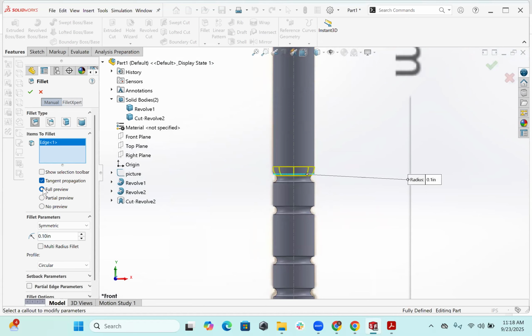I'm gonna hide my image so it's easier for you guys to see what I'm doing. Looks like I got everything. Let's check. All right. And if you click the eye again, the image, or if you have planes, they'll show up. Seems good. We have two bodies, two parts, and if you guys really like to, you can add appearance to this. So go to the round colorful ball, open appearances and organic. I think wood will be under organic. Here we go.